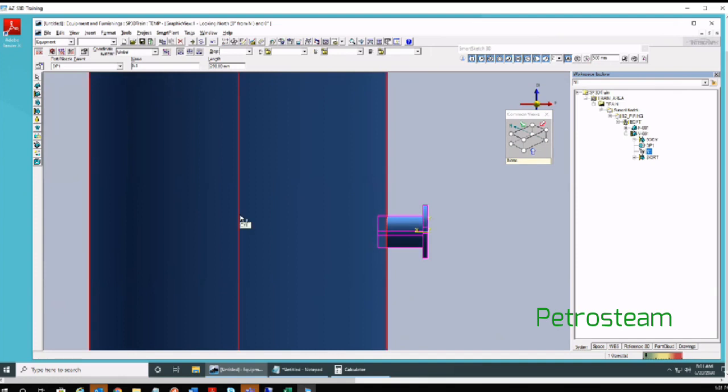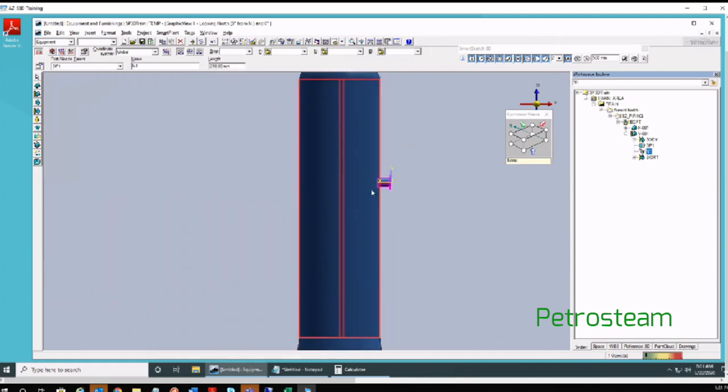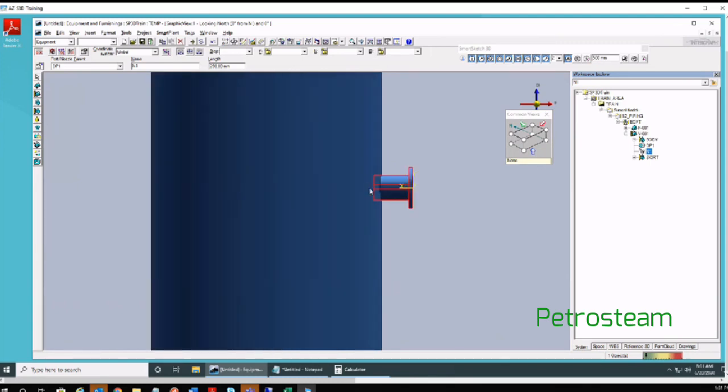Maybe because of that PDMS program, they requested you to give the total length from the center. In this SP3D, for us, if it penetrates the cylinder, that's enough. So you make sure that it's penetrating the cylinder. Any other questions till now?